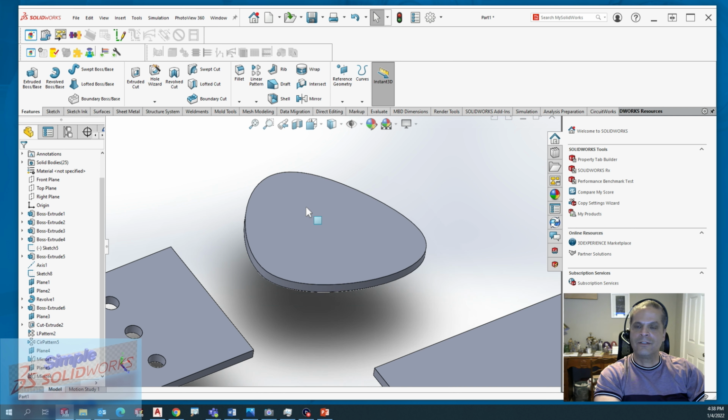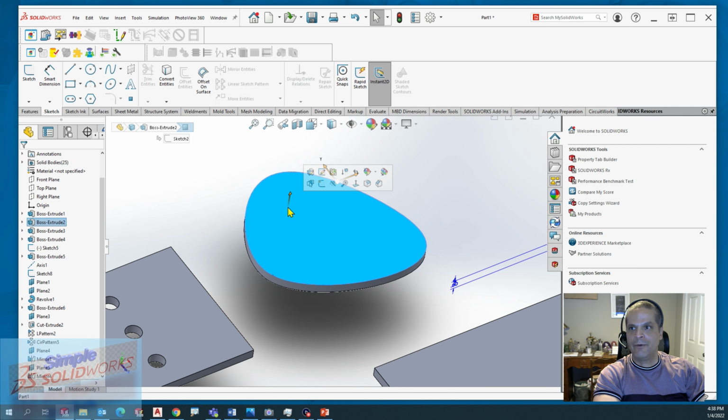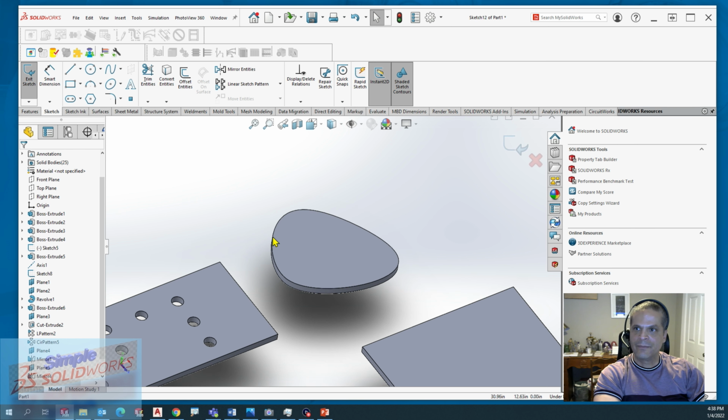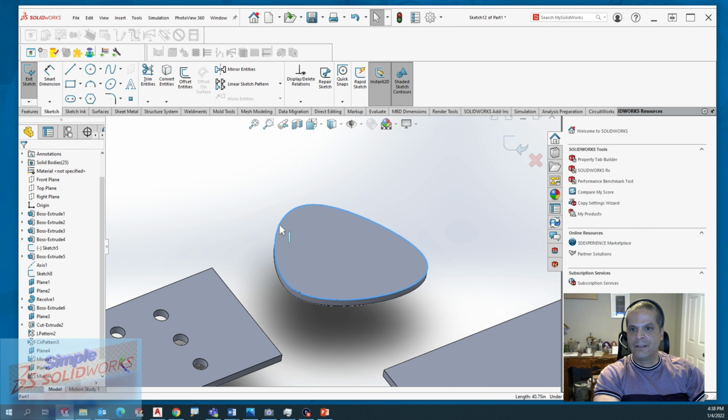All you're going to do is create a sketch. I like to do it with a sketch first. I like to pick on this plane here, and that's where my sketch plane is. I'm working on that plane now, right? I'm active on that plane, and I like to pick on this edge here, and then convert it. So I have a converted edge going across that follows it all the way around.